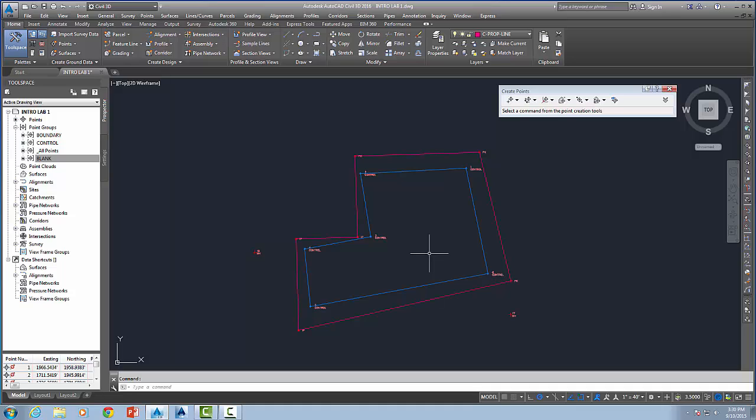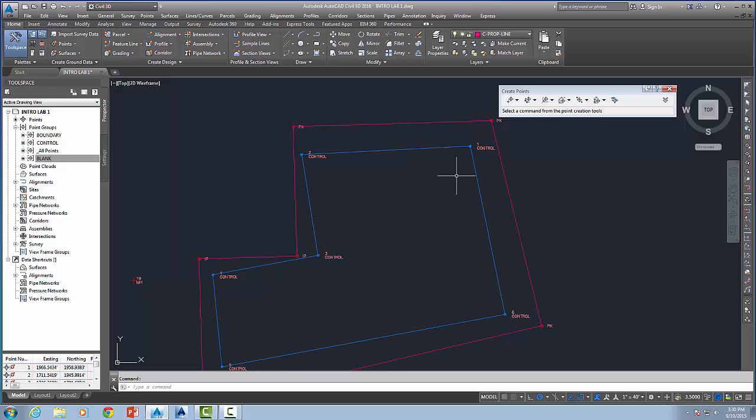And point 18 is an intersection of two distances. And the one distance is coming from point 1 down to 18, and the other one is coming from 3 down to 18. So this is commonly referred to as a distance-distance intersection. Some people out in the field, they call this two-taping, where you're taping two directions. It is an okay way of locating points. It wouldn't be something you use a lot.